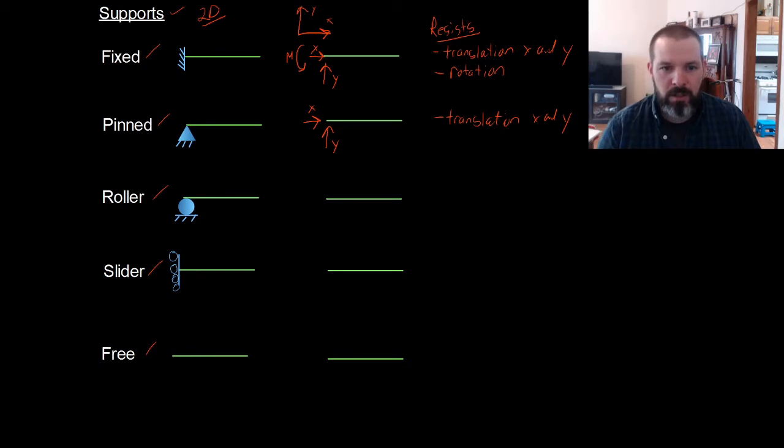All right? So if we wanted to come over here and lift this beam up, we can easily take it and move it from here to here without generating any force. If we tried to do the same thing with this cantilever, it wouldn't allow us to rotate here, so we'd end up bending the beam.